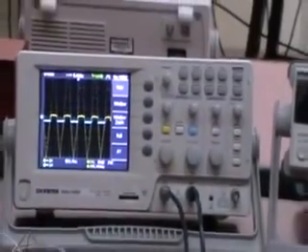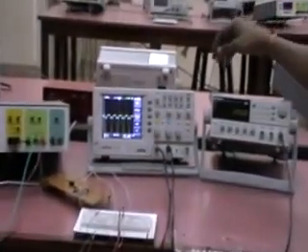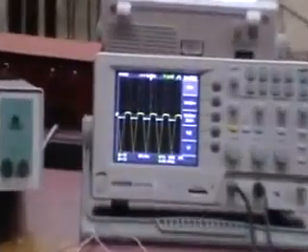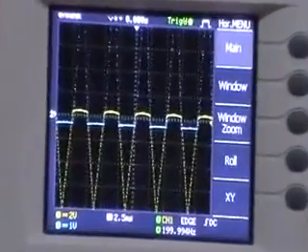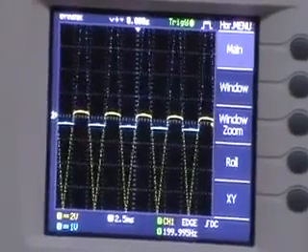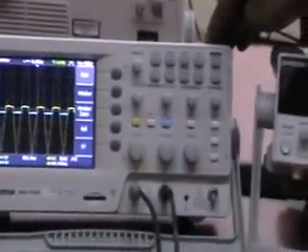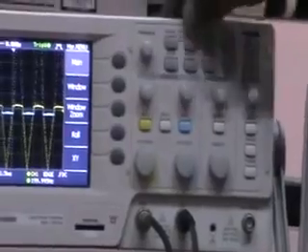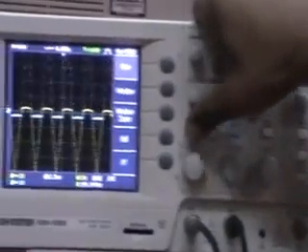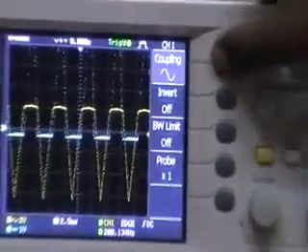So you can observe these are the two output waveforms of both channel 1 and channel 2. So we should observe the IV characteristic in XY mode. To observe waveforms in XY mode, first we should keep the dot across the center. We can verify this by keeping both channel 1 and channel 2 in ground modes.